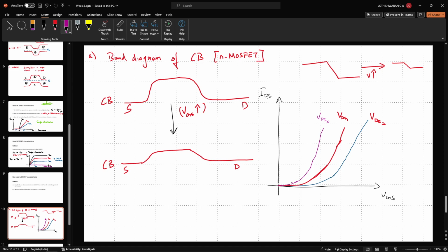So what we will actually need is to distinguish this. We will need to find out a gate voltage where the increase in the current is so high between the off state and the on state that I can clearly distinguish them. So that quantity is given by this derivative. Now I want the current to change. I don't want it to change by a factor of 2 or a factor of 3. I want it to change by orders of magnitude.